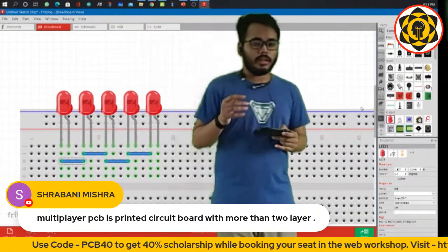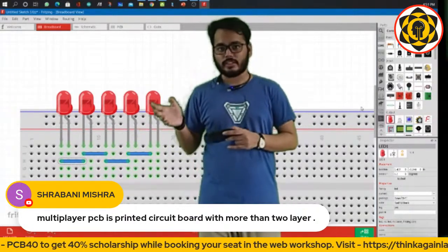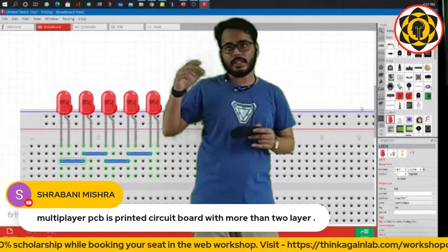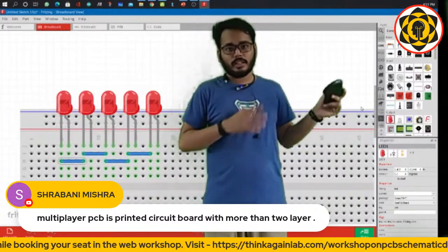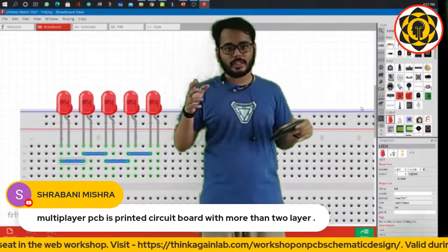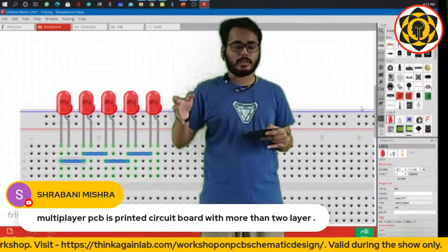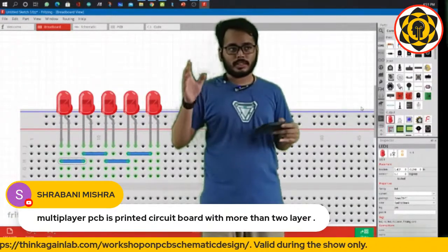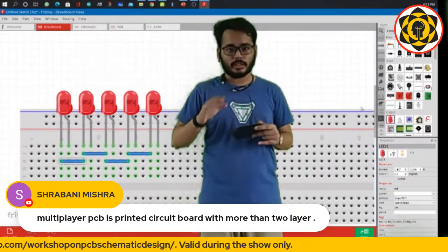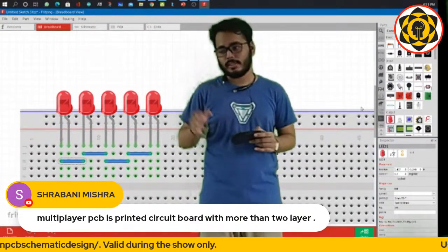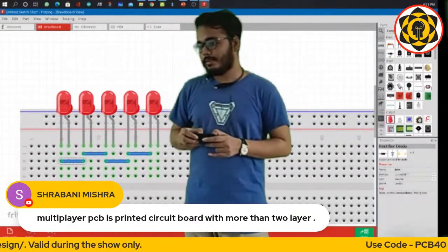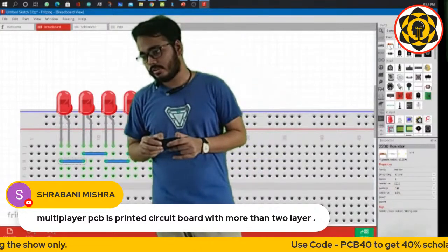Next, these LEDs need current limiting resistors, because, let me give a TLDR to the people who are not from electronics, an Arduino supplies 500 milliamps, and these LEDs only need around 30 milliamps. So it's a lot more current, which in short is bad. The LEDs will just go boom. So to prevent that, let me put in current limiting resistors.